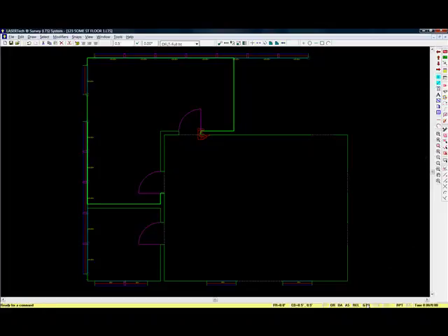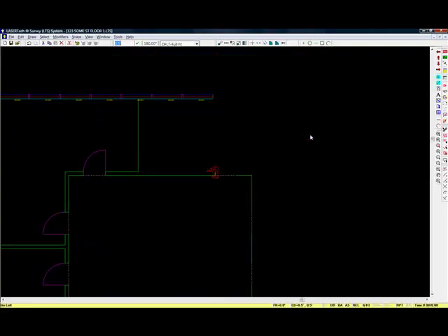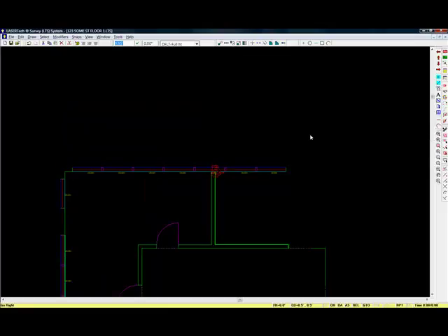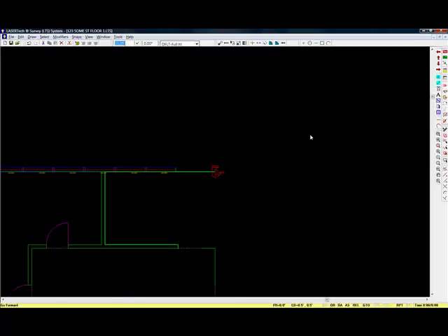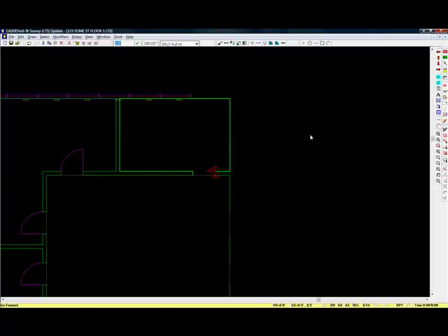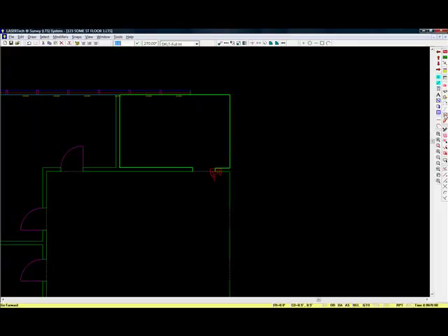So we do a go to, we move our surveyor here, measure the wall thickness, it's again 0.5, we turn and we go 10 feet, and we go up 9.95, let's say, and then we turn and go 15.05, and then we come down 10 feet, and then we turn and go 2 feet, and then we would match the door jamb again, and we're ready to do another closure.